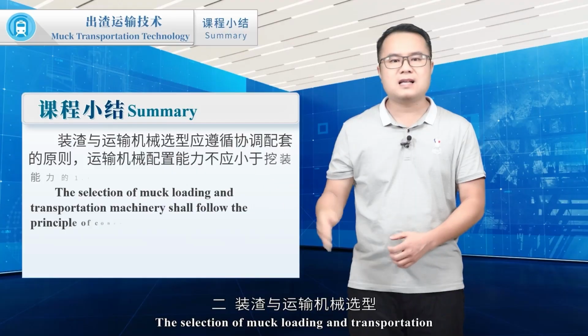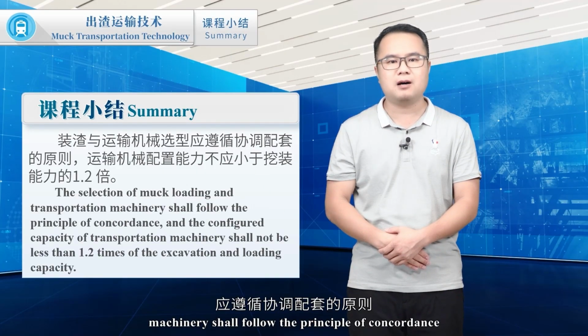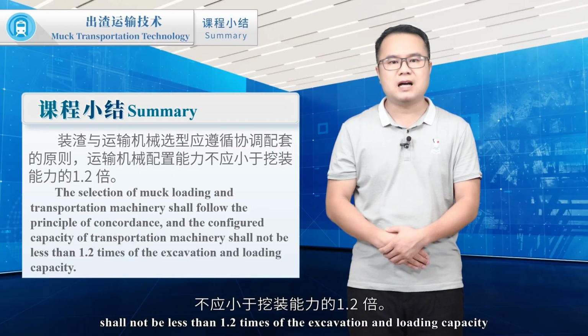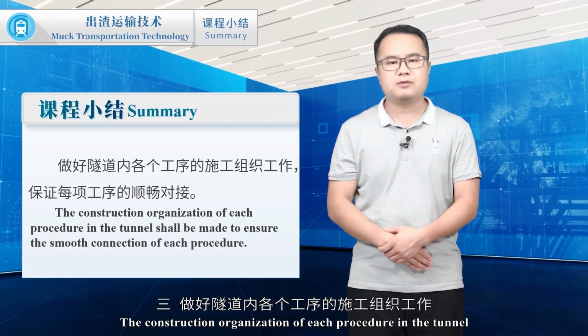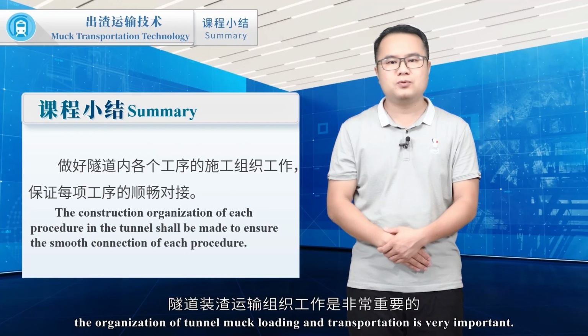The selection of muck loading and transportation machinery shall follow the principle of concordance, and the configured capacity of transportation machinery shall not be less than 1.2 times of the excavation and loading capacity. 3. The construction organization of each procedure in the tunnel shall be made to ensure the smooth connection of each procedure. It can be seen that the organization of tunnel muck loading and transportation is very important.